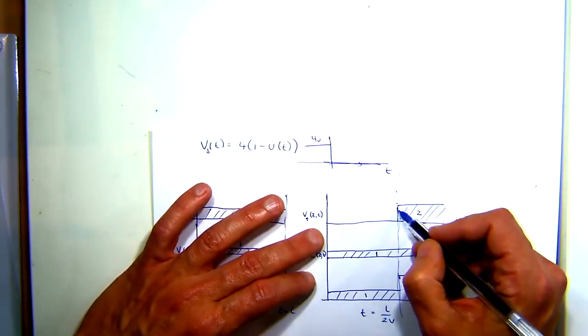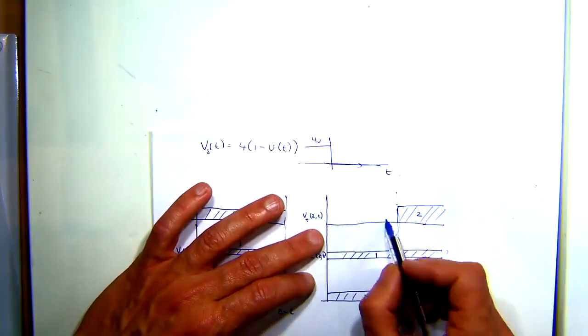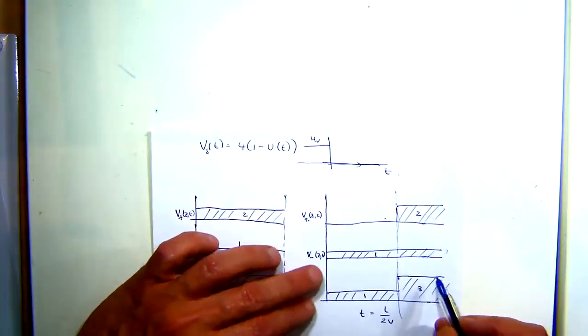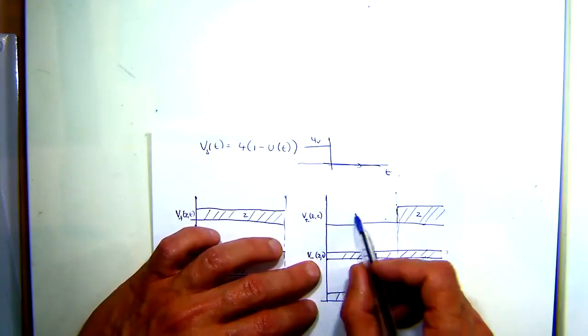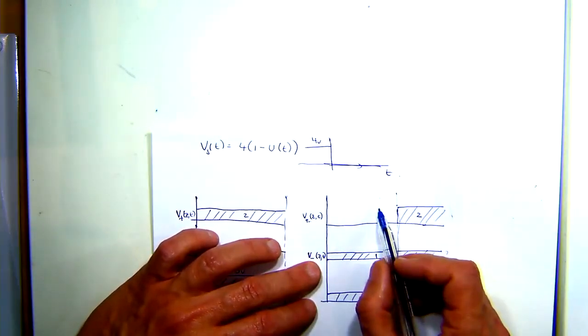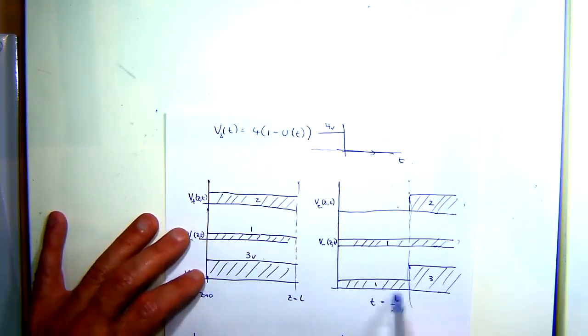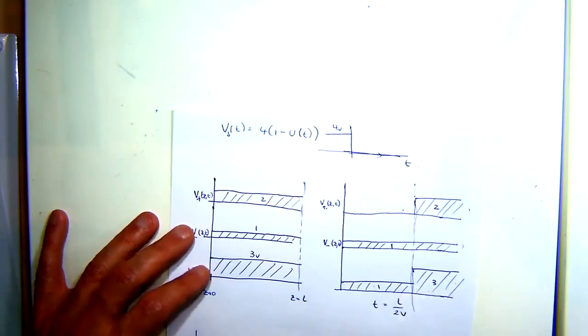But this is only as far as this disturbance has moved in that time. So it's 0 here, 2 volts for the positive going wave. Not enough time has occurred for the negative going wave to be modified, so that remains at 1. And our disturbance, or the transient on the line, is 3 volts in this section, 1 volt in that section.